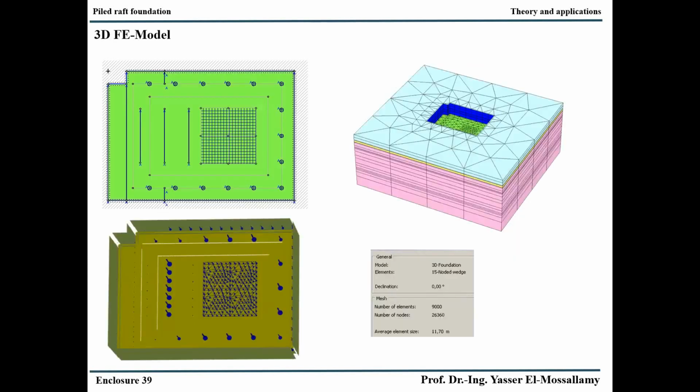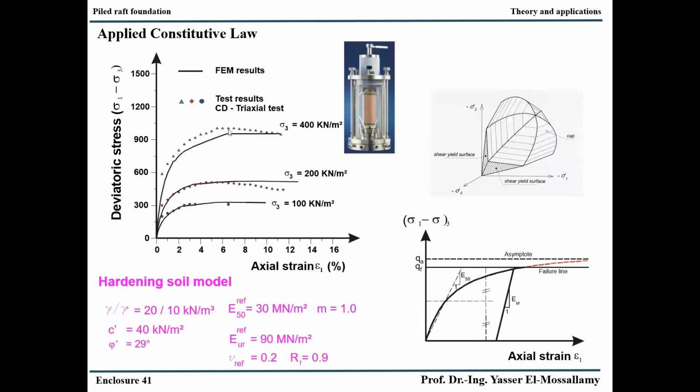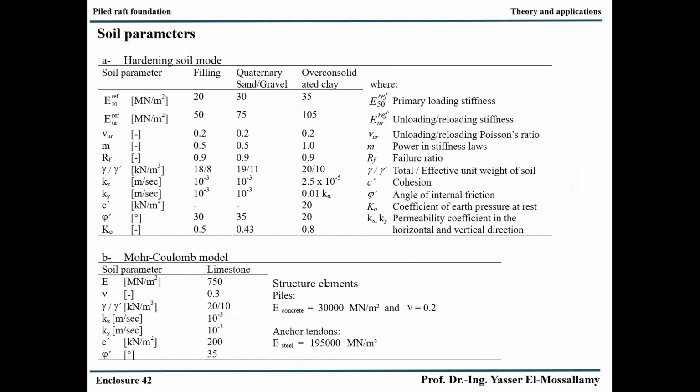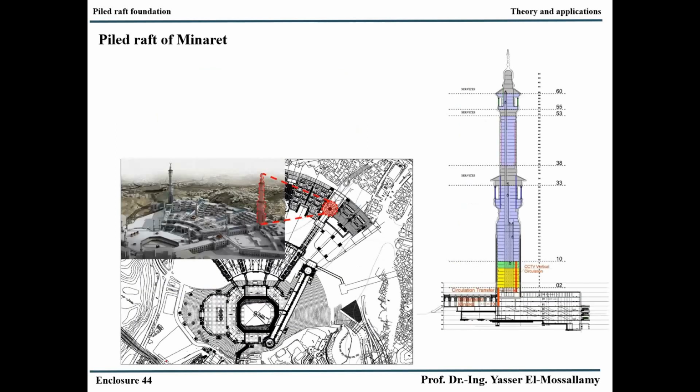And we also helped our colleagues in Poland to calibrate their model, and we used one of the high-rise buildings in Frankfurt as the basis for this evaluation. Most important are the soil parameters, and we have very nice lab tests and data in Frankfurt. Therefore, we can do this calibration in a very accurate manner, and you can see that we get really very good results. Then we have high confidence in the development of these beam element or embedded beam element models in Plaxis, and these are also applied now in other software.